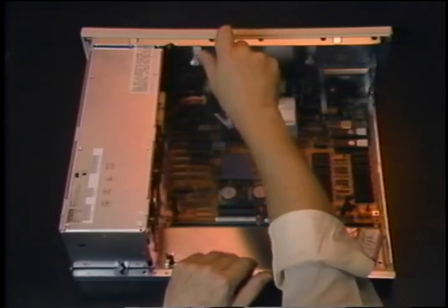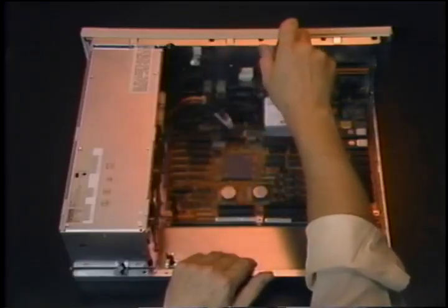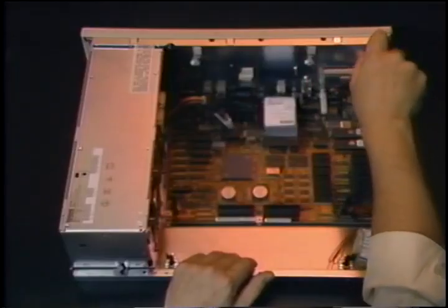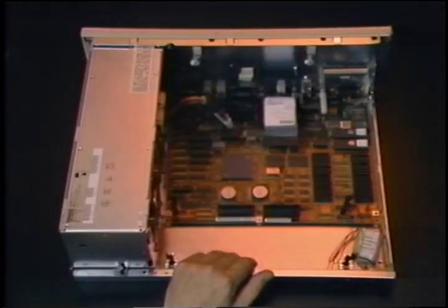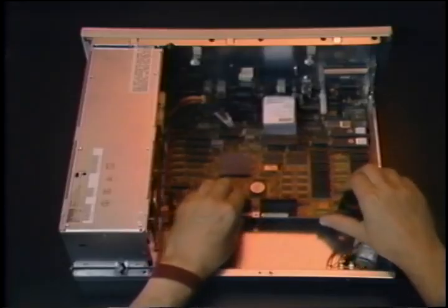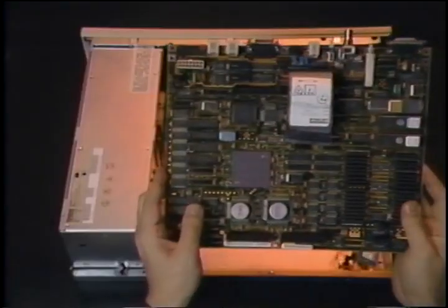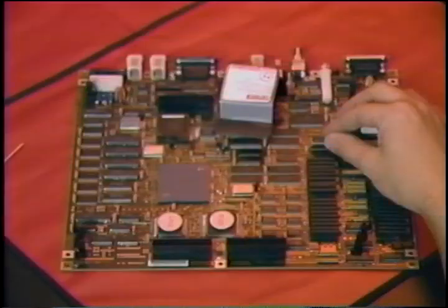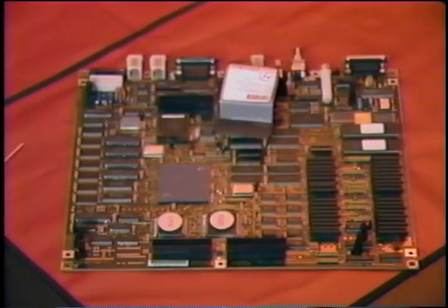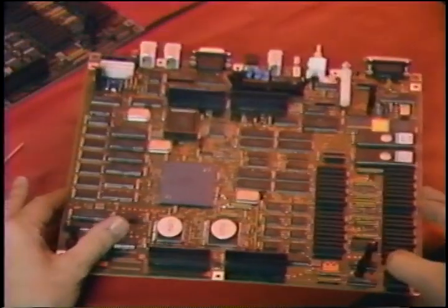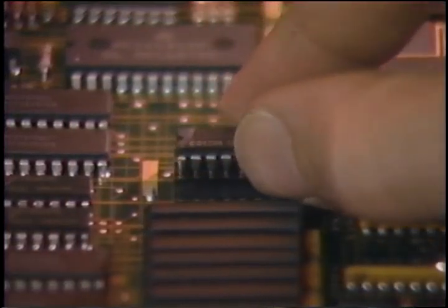Eight Phillips screws hold the KA42. To preserve the physical Ethernet address of this or any VAXStation 3100, always remove and insert the ID-ROM on the replacement KA42.